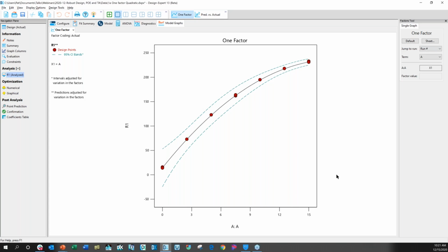Okay, so doing the propagated error and having the ability to look at the transmitted variance and look for where that's lower comes at a very low cost. The only cost is not more experiments, not more analysis, just figuring out what the expected variation in the inputs are, knowing those sigmas. And many times you can get those from existing gauge R&R studies or literature, or do a little study and estimate them yourself.